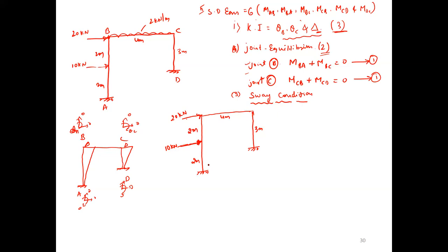See, generally we are getting a moment MAB and also MBA. Ignore the beam, only consider the column. Here you are getting MCD. Initially, whatever the direction is, no matter, assume all clockwise. So these are the final moments, MAB, MBA, MDC, right?